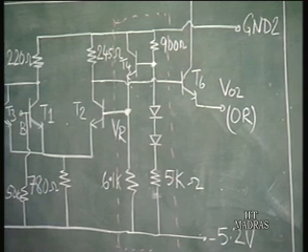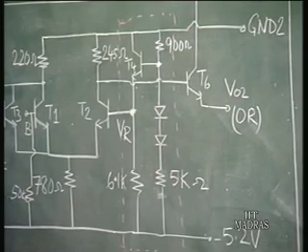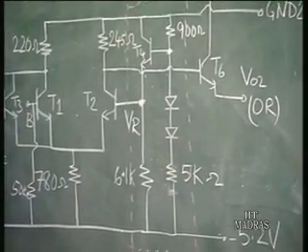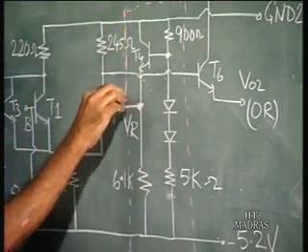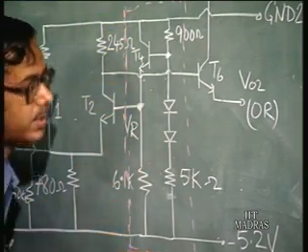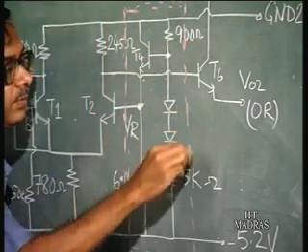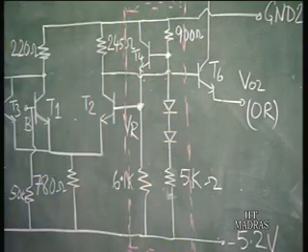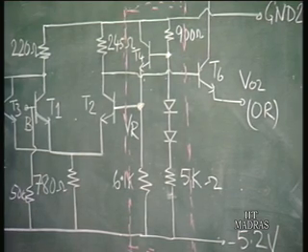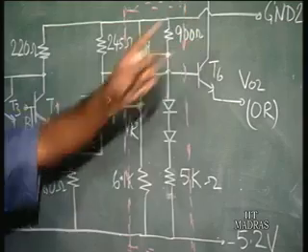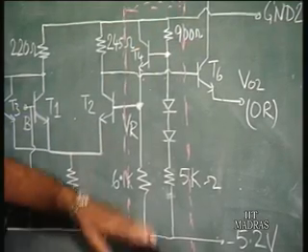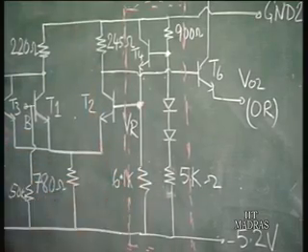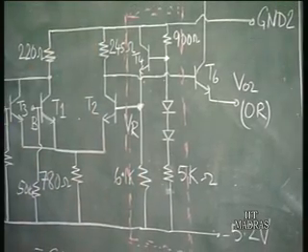You do not have a separate voltage input for reference voltage, but this is generated internally in the chip from the power supply. So, this part of the circuit generates the reference voltage, and we shall discuss that. The other interesting thing about this circuit is that you have 2 ground connections. Normally, you have the 2 terminals for the power supply, but here you have 2 ground connections.